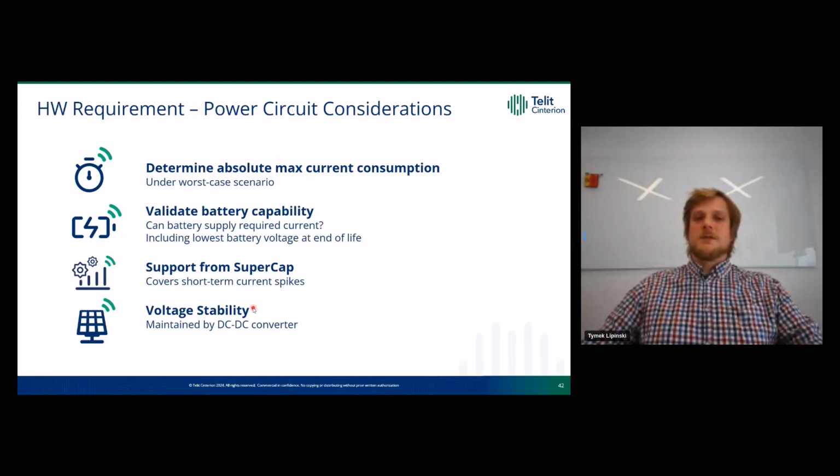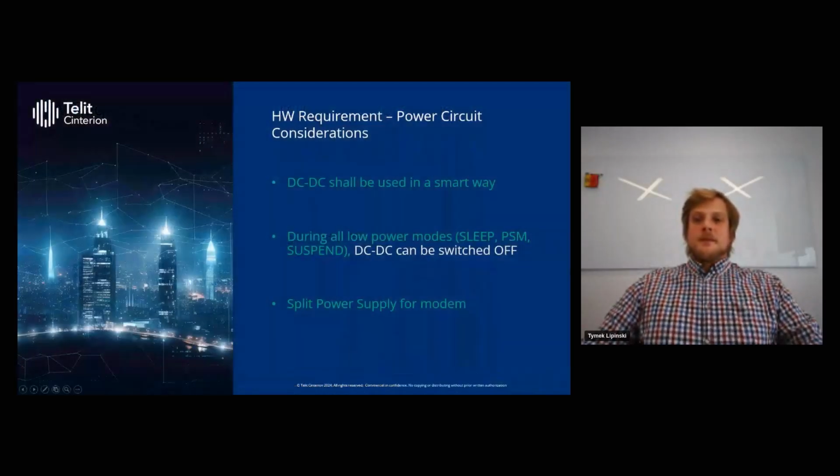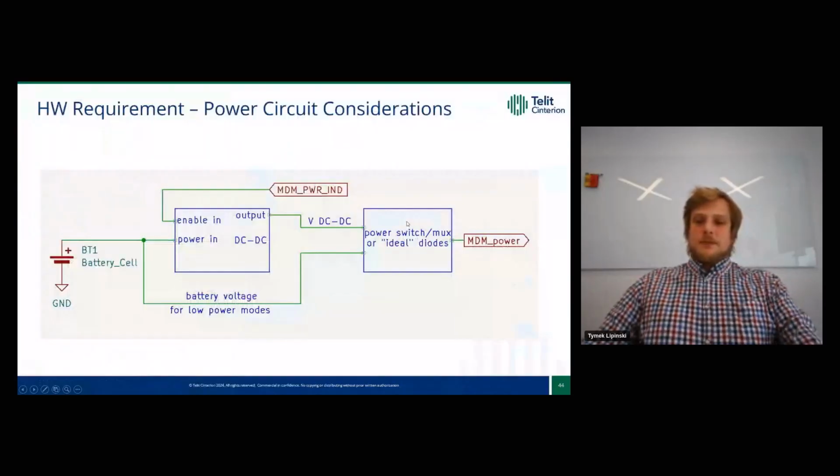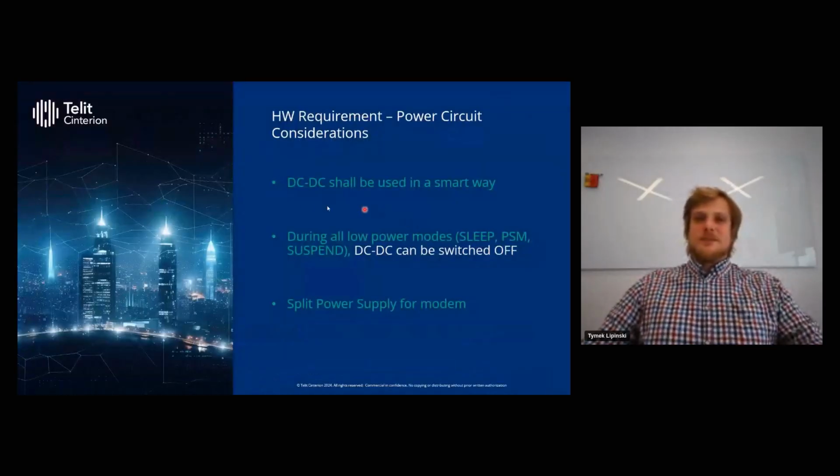Ultimately, we go with voltage stability. This can be maintained by a tailored DC to DC converter. The DC to DC converter shall be used in a smart way. Modern DC to DC converters provide a wide variety of modes of operation: CCM, DCM, PFM. Most interesting one is PFM, pulse frequency mode.